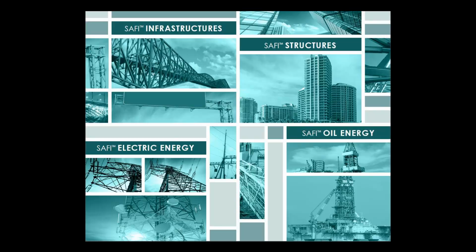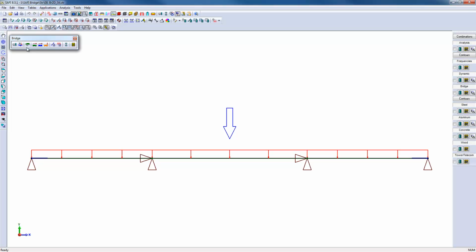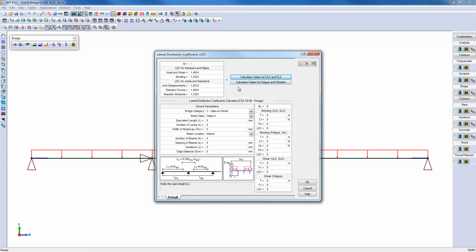This short tutorial will show you how to associate a lateral distribution coefficient to a simple bridge in 2D. When the bridges are sufficiently simple to be modeled in 2D, we must associate a lateral distribution coefficient to the moving load. A lateral distribution coefficient represents the ratio of a truck that will be associated with the modeled beam in the 2D model. In the example below, the axle factors were initially specified manually.